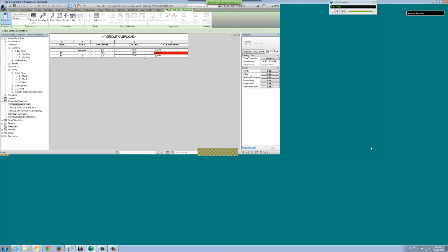And again, if I want to change the rating here, I'm seeing this live, which in a panel schedule I don't see. Yes, I can change the rating of that circuit, but I'm not seeing that initial effect on what's connected to it. So being real time there, I can see that update, make a change. Again, that's that VAV box sitting inside of there. So obviously I need to work on this one. We know it's way above the 166 anyways.